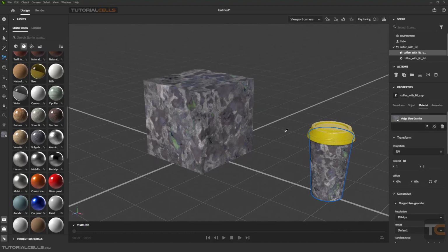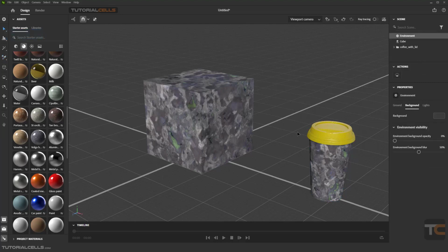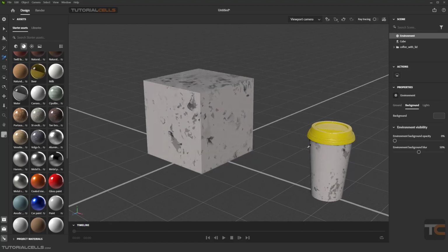Nice. Be careful, you have to go to select mode or V, deselect everything. But if you want to just transfer the color, for example, this color to that, you have to go and select the color picker and select this color or maybe this color. As you can see, this is an RGB. And then holding shift and click there. And it just transfers the color of that. Be careful about that. You have to deselect everything. Nice.